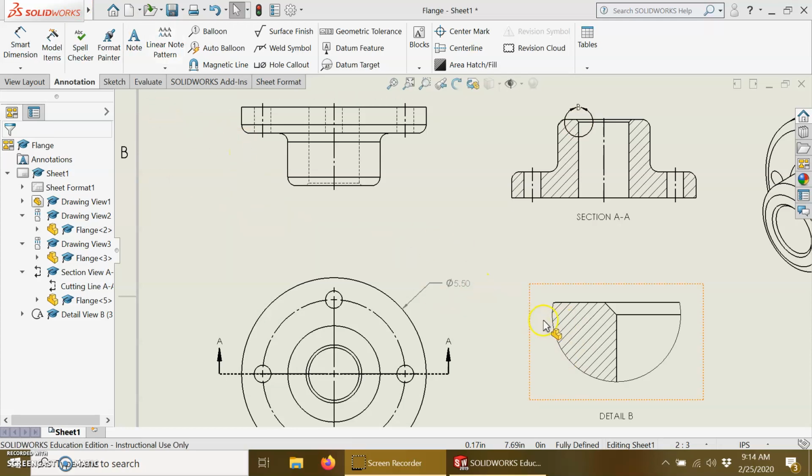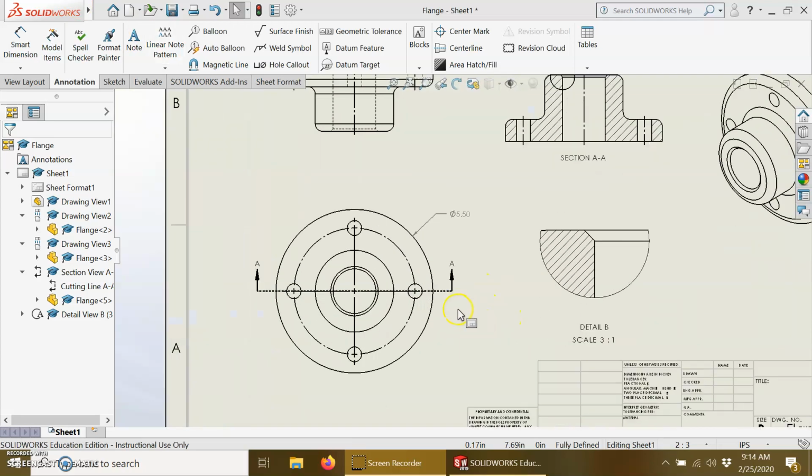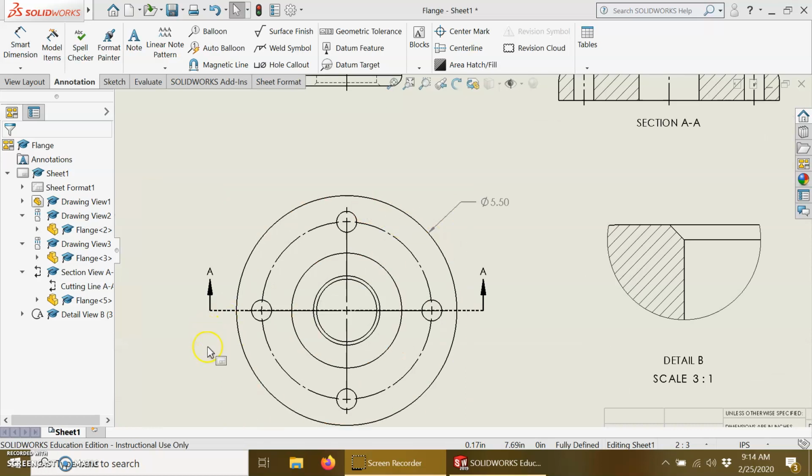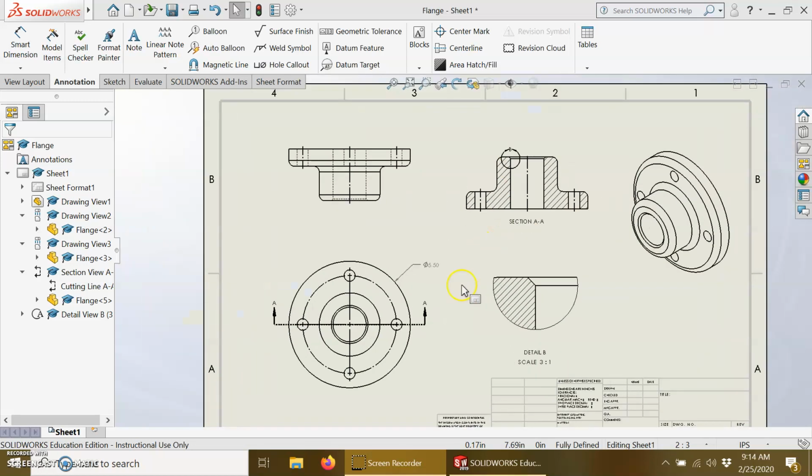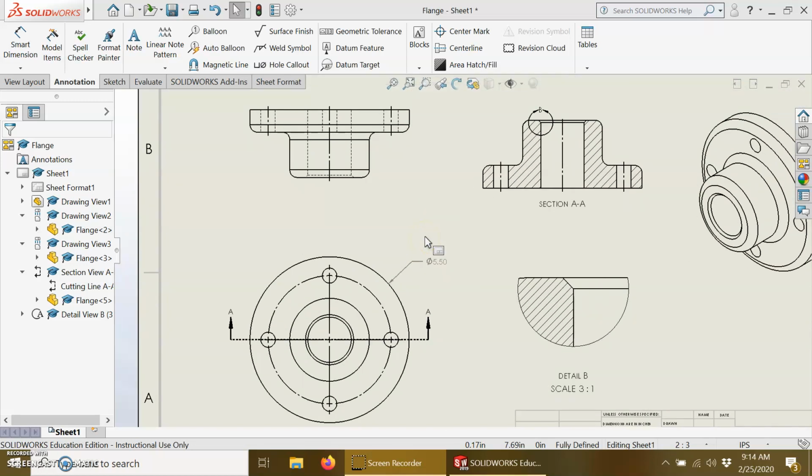Actually, the whole ISO ANSI thing, another thing that should have tipped me off, but I wasn't paying attention: you'll notice before, the arrows showed kind of pushing the cut line, whereas in the ANSI drawing, they are pulling the cut line. So we've made that change. Let's go and start dimensioning the rest of this guy here.